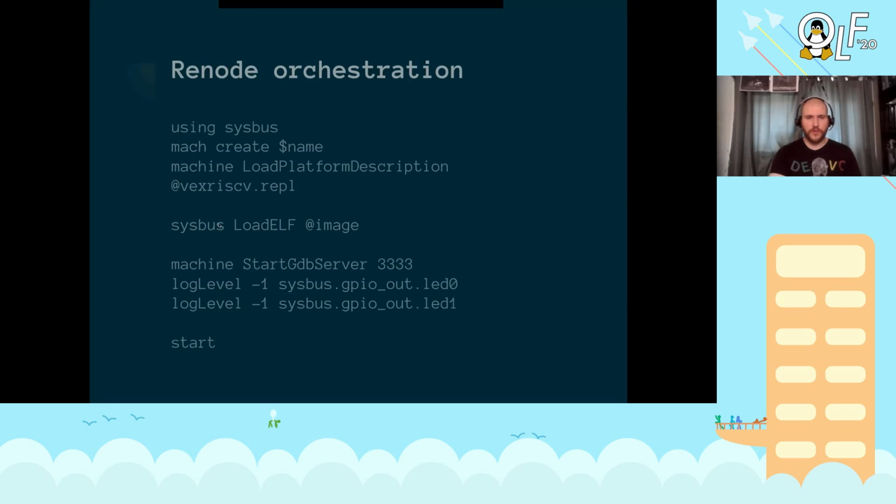And then we load into that machine an ELF image. So it's actually the same exact file format. We don't use a custom bare-metal format or raw binary. We use an ELF format. And Renode knows how to load that and put that into memory for us. So it knows where the memory starts, and we are able to load our image directly into memory. And then the CPU has a certain location where it knows to start executing from. So it's not main, but it's an actual memory location, I think 0, or maybe it's a different jump address.